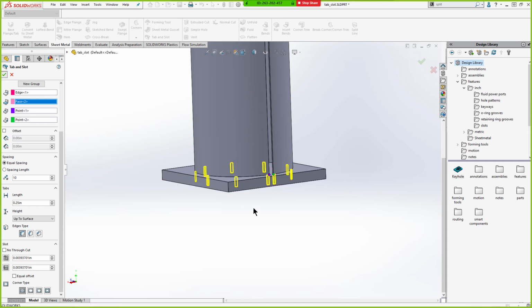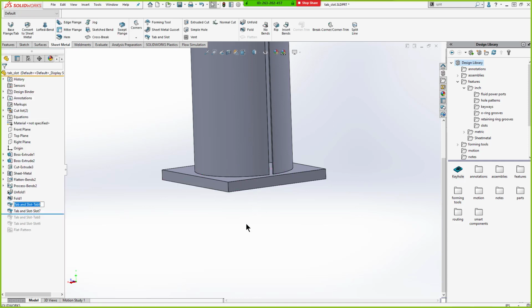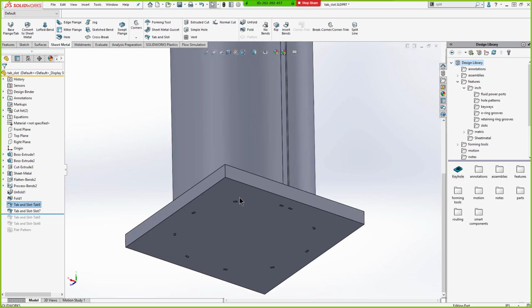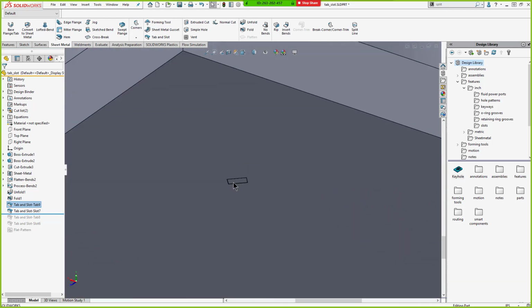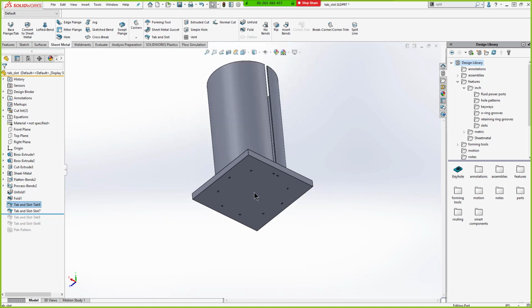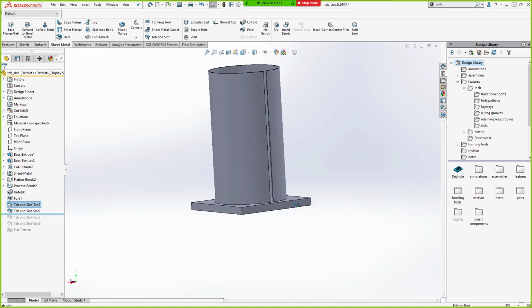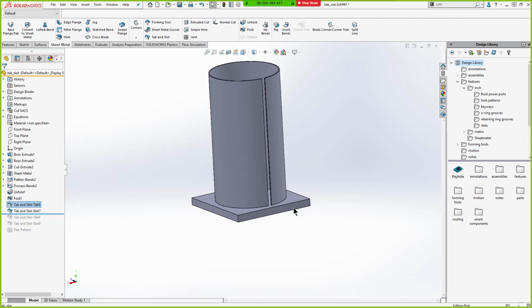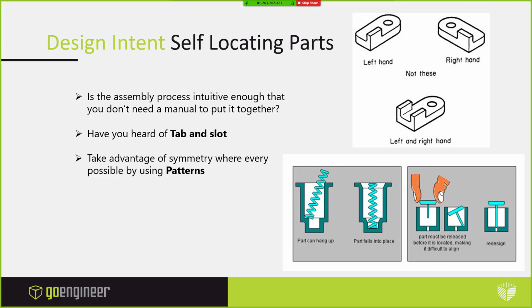So we go ahead and click the green check, and then you could just drop this in, and the guys don't really have to make mistakes with their tape measure, and you could just plug weld these out on the bottom. So if you have a water jet or plasma cutter or something like that, this is an ideal way to pre-cut your material so that you can align it a lot easier and make fewer mistakes. But also, I just want to showcase tab and slot. I think it's a pretty cool tool.